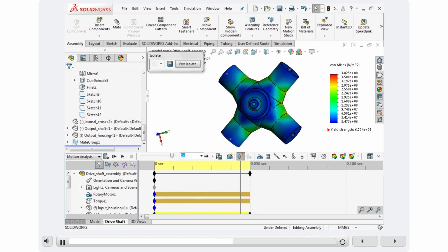The stress contours are now visible. The indicated maximum of 383 megapascals is below the yield strength of the material, 620.4 megapascals. The difference in results from this simulation to the last is due to the differences between the mesh. Similarly, we will plot factor of safety. Click Results Plot and select Factor of Safety Plot.